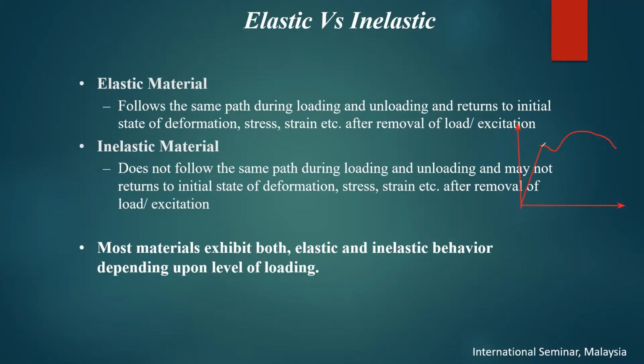I remember this one is familiar for yielding. Here you are going for yielding. This stage, we call it the elastic stage, or the linear stage. So for example, when you give a steel rebar and put it under tension or tensile stress, if, for example, the rebar is 420 megapascal yielding, and it reached before 420 megapascal and you release the loading, it will return to its initial zero path. So this is the elastic range. This can be the plastic, and here's the rupture.